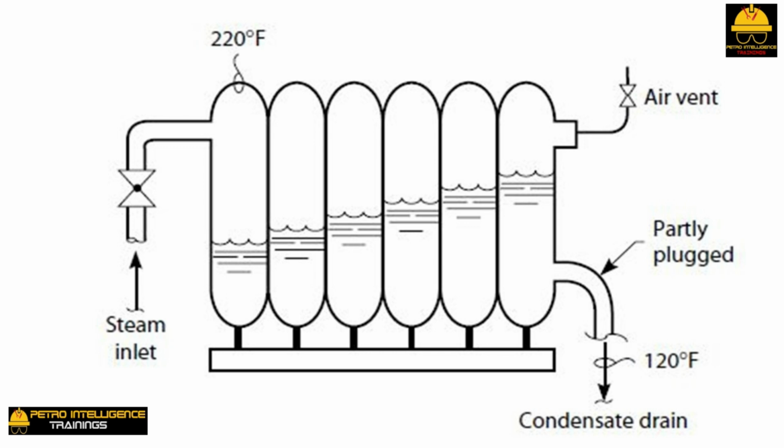It rather seems that 40% of the surface area of the radiator in the picture is submerged underwater. If the water is drained out, does this mean that the rate of steam condensation will increase by the same 40%? Answer is yes. Does this mean that the radiator heat transfer duty will increase by 40%? Answer is not quite.